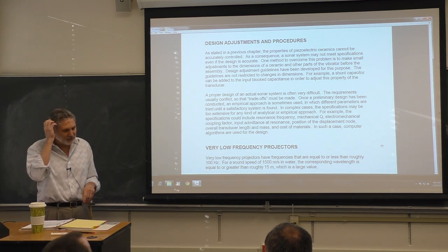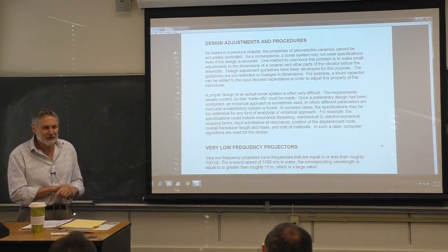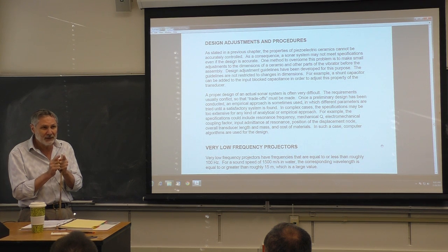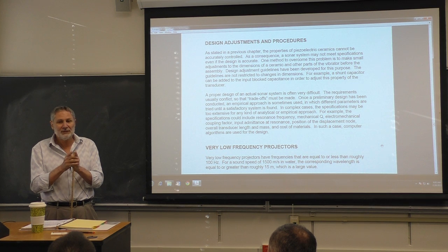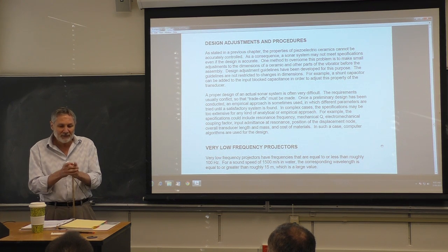There are, you can buy precision microphones, and two of them if you need two. For example, suppose you want to look at the difference voltage in order to come up with a vector sensor. I think we've talked about that in the last. And to look at the difference voltage, you precisely need these two transducers to be the same. And I've done this before, and they were. The sensitivities were the same within 1%, okay?